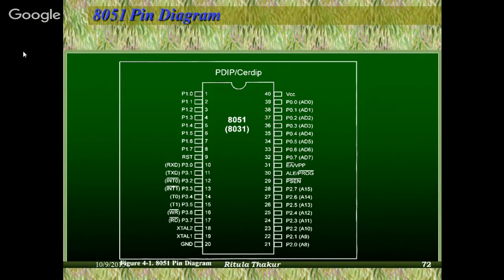And coming back to this, there is another advantage of a microcontroller or microprocessor, that in this case you have single bit addressability. As you can see from here, pin number 1, it's written P1.0. What does it mean? P1.1, 1.2 से लेकर P1.7. There are total 8 pins, na? In every port there are 8 pins. So there are total 4 multiplied by 8, that is 32 input output pins. So in this case you have single bit also.